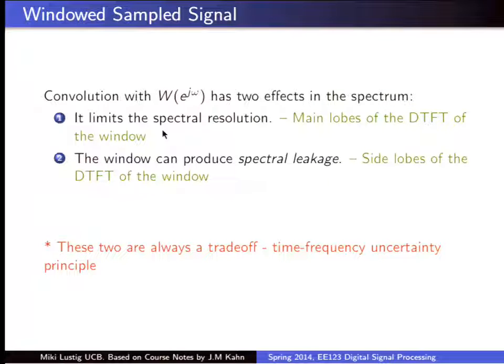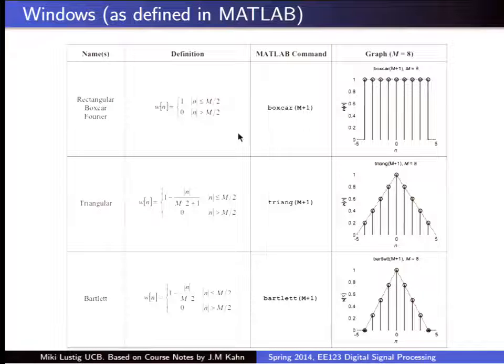So we're going to look at different windows. People have looked at different windows for this analysis. Okay? And the classic teaching of DSP is they show you all those windows, and then they tell you here's the optimal one at the end. Why go through all of this? Because sometimes it's just easy. And in many situations, people just use certain types of windows. So it's good to be familiar with them and what their properties are. Some of them are ad hoc. But these days, we know how to generate something based on optimality criteria. Okay? And it's actually been resolved a long time ago, too. So here are some examples. A boxcar, which is a rectangular window.